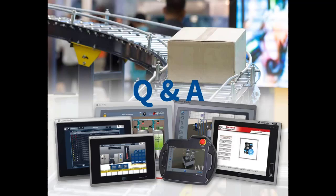There are some older compact logics, the original series, like the L3 processors, L2s. It does not work with those. And it also does not work with any of the 1768 processors. So there might be some workarounds using Modbus, but I really wouldn't recommend it. You really want to work with one of our newer processors there.